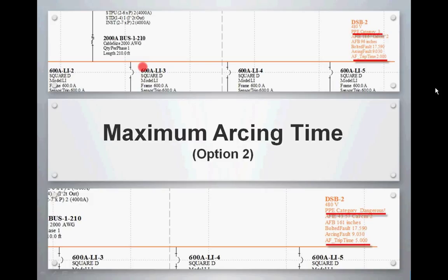The breakers, feeder breakers are pretty big, so it's definitely a switchboard. And we have here the case when you have a, let's take this little terminal panel out of the way. The trip time, it's covered perfectly well. Let's see, no, I cannot move the little panel. So you would have to tell me, I know that in this situation it's a trip time of, oh boy, I wish I would know. Probably 2 seconds. The upper side is 2 seconds. And this is 5 seconds.